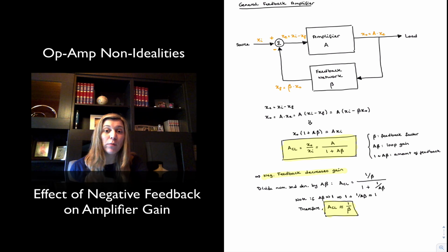Even for the same op-amp, if we were to look at the datasheet, they might give us a maximum and minimum value, which more often than not, they'll just give you a typical value. But we will see that there is a lot of variation, a wide range. And the reason for that is because it's a parameter that gets heavily affected by process variations.